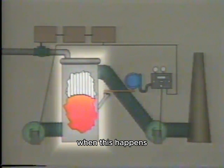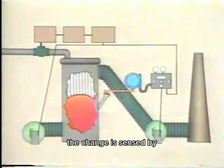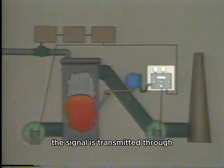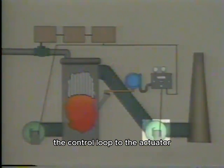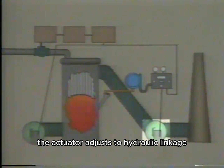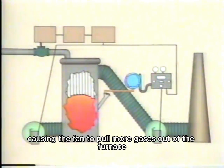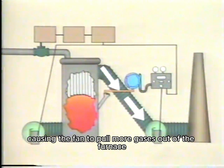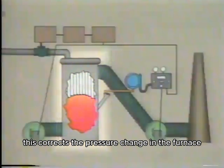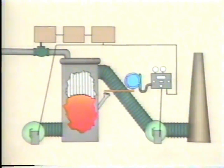When this happens, the feed-forward control loop comes into account. The change is sensed by the primary element of the control loop. The signal is transmitted through the control loop to the actuator at the ID fan. The actuator adjusts a hydraulic linkage which increases the speed of the ID fan blades, causing the fan to pull more gases out of the furnace. This corrects the pressure change in the furnace and maintains proper airflow required for safe operation.